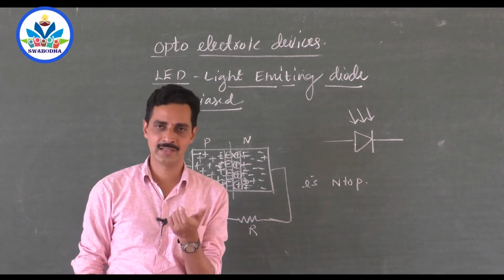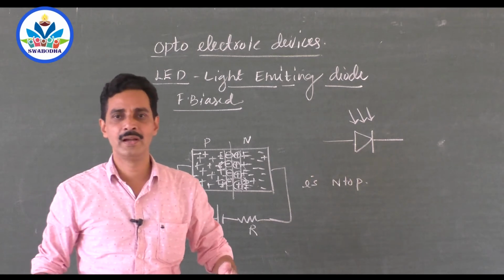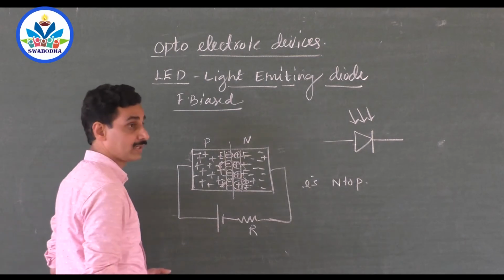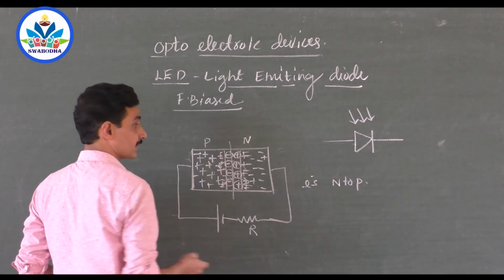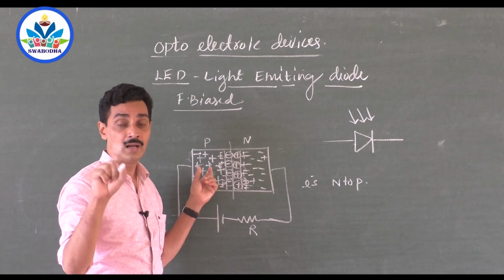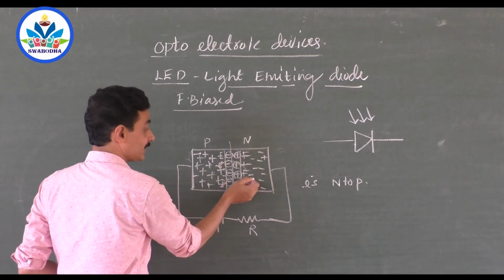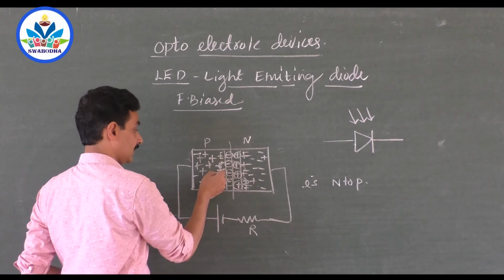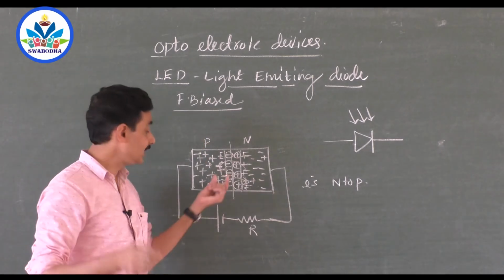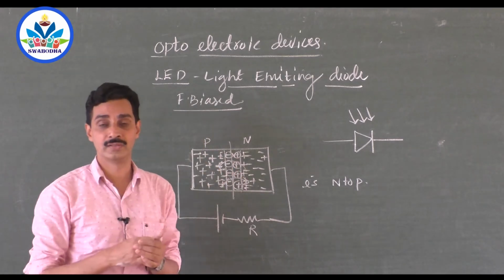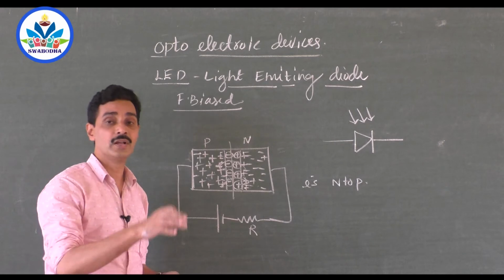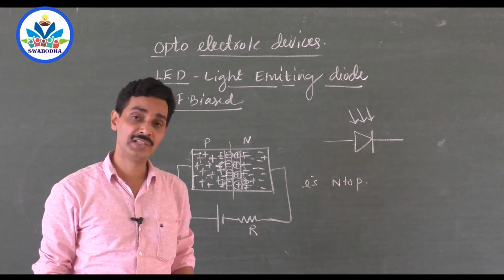Near the depletion layer region or near the junction, there is a crowding of these minority carriers, and they can combine with the majority carriers. You know what these are? Boron atoms, trivalent atoms. They have a scarcity of one electron for filling the bond, right? When electrons in the N region move to the P region, they become minority carriers. Here holes are the majority carriers. They are waiting for the electrons. These electrons can combine with the holes. What do you mean by that? That hole may be filled with this electron which has come over here. Electron fills the hole.